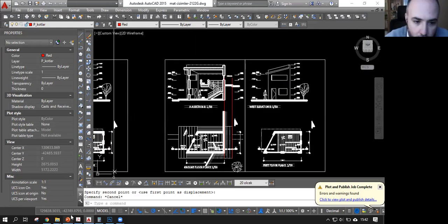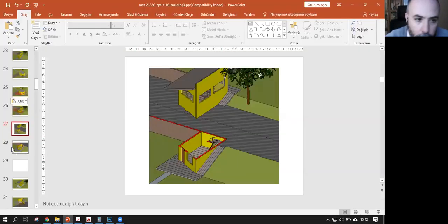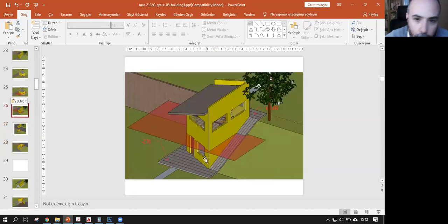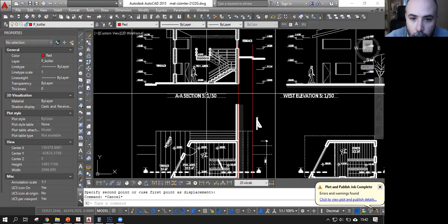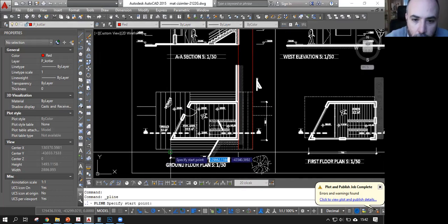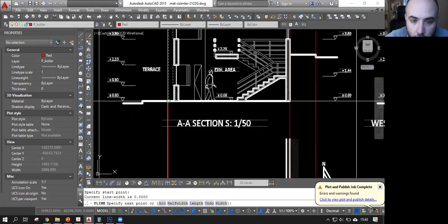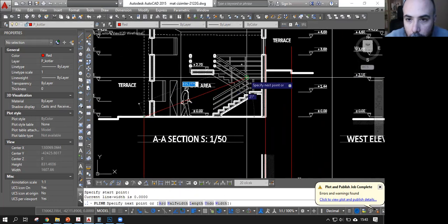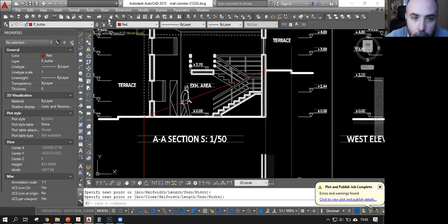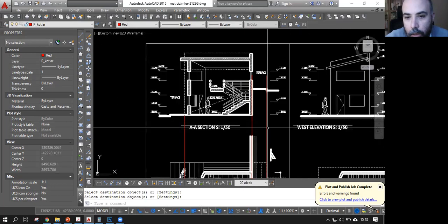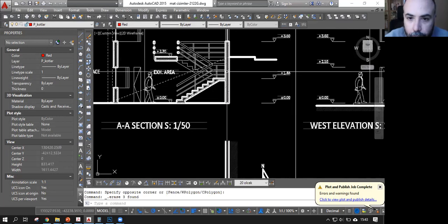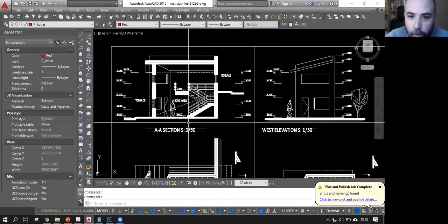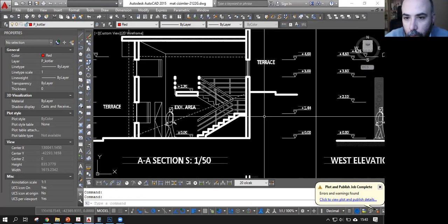And I can just indicate this sloping surface at my back with dashed lines too. So this is what I need to do. That sloping surface starts from here, so I can transfer it to my plan, and it ends here. And this is how I should show it with these dashed lines. That's all. And after that, I can just create the hatch one more time to indicate this Earth surface.